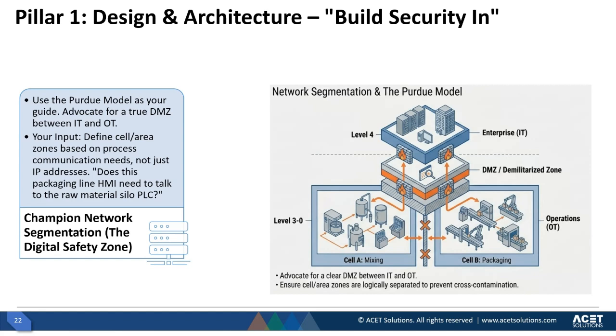Also, whenever we need to connect with the IT side, we need a DMZ layer, and this DMZ is very important when connecting with IT or the internet. In the past, in some cases people used modems to connect directly to the OT and download or upload reports for management. That era is gone. Now we need a proper demilitarized zone between IT and OT. So even if today you are doing the same practices, you have to change yourself.